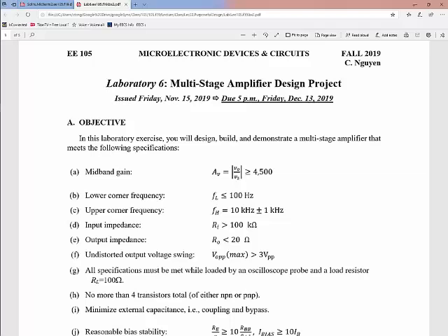And the gain here is so high that it's possible that on your breadboard you can get things like oscillations that we'll talk about, which means you've hooked everything up nicely and it should work, but instead of working, it's just oscillating with some huge sine wave, even though you don't put an input signal in. And that way you're basically creating an oscillator, which is a very important circuit.